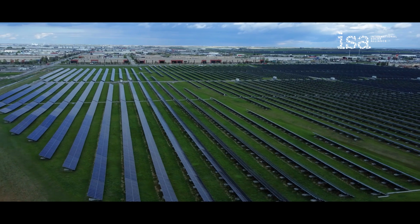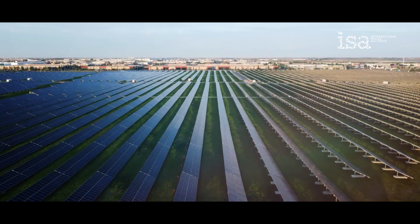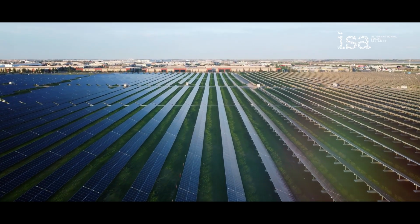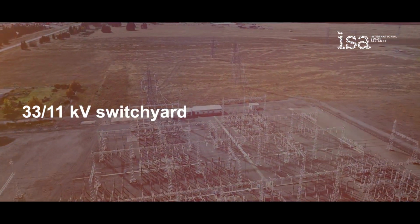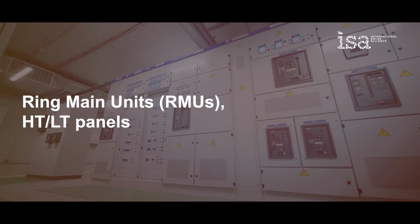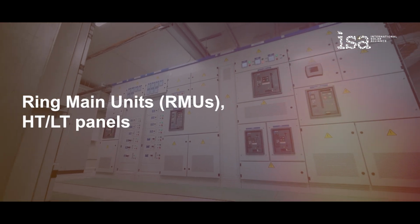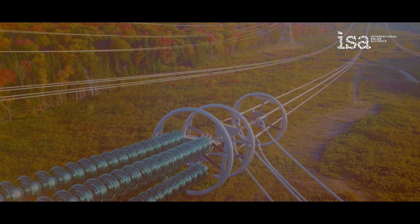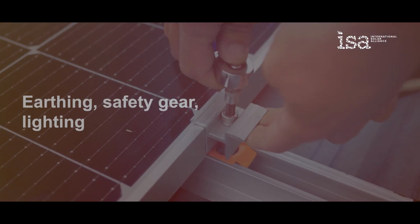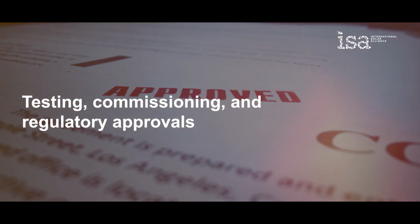A large solar power plant, say of 5 megawatts capacity, includes specialized equipment to manage power evacuation. 33/11 kilovolt switchyard, ring main units, RMUs, HT/LT panels, transformers, power/control cables, earthing, safety gear, lighting, testing, commissioning, and regulatory approvals.